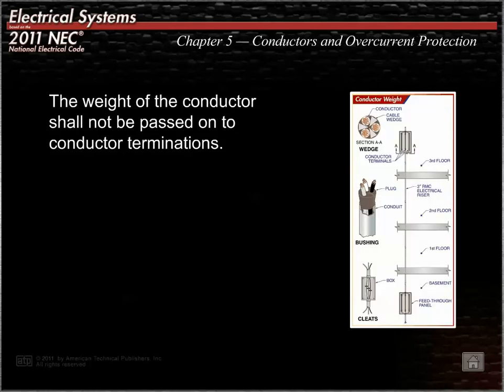Section 110.5 requires all conductors used to carry current to be copper unless otherwise specified by the NEC. While copper is most extensively used, its cost is a primary disadvantage. The cost of installing electrical distribution systems with copper conductors, primarily in large sizes, can be very expensive.